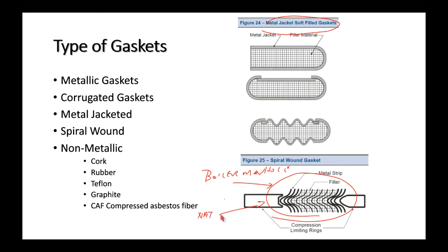natural gas. And they likely use these inside the lab for our natural gas piping where we have got a gasketed flange. So what you have is a whole series of spirally wound, actually it's just a single spiral wound sheet that is in that shape. And so they wind that, it's usually like a stainless steel or something, wind it around multiple times, and then they put a filler material in between all of these windings. And so the flange face compresses on it.